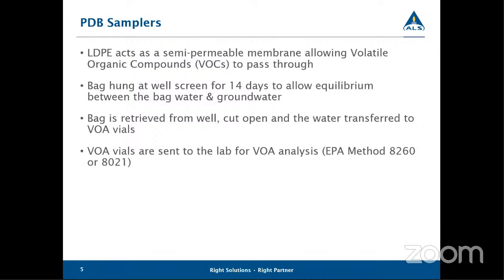And that's definitely one of the strengths here, for long-term monitoring situations where you might be going out on site, call it quarterly or semi-annually, even annually. You can go out, deploy your passive diffusion bag, come back the following quarter, it'll be in equilibrium, retrieve it, collect your sample, and go ahead and deploy the next one for the following quarter. So they can be virtually left deployed indefinitely, and because there is constant equilibrium being reached through that membrane,